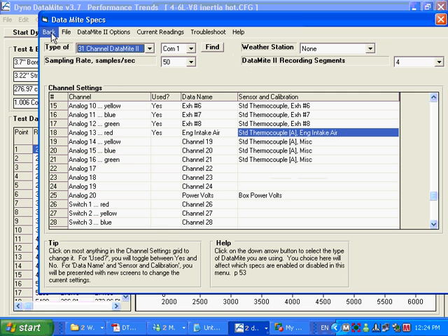The barometer at the box, the DataMite, and the engine are the same. The barometer is exactly the same. The humidity is, for all intents and purposes, almost identical at the box, the DataMite, and the engine. But the temperature can be significantly different. And so that's one thing to improve your correction factors, to have a separate air temp thermocouple over at your engine.